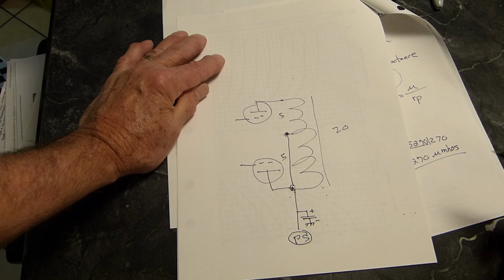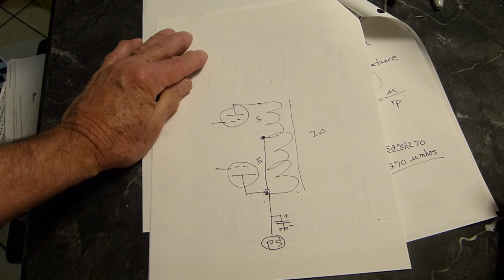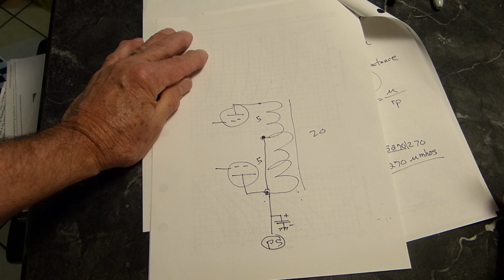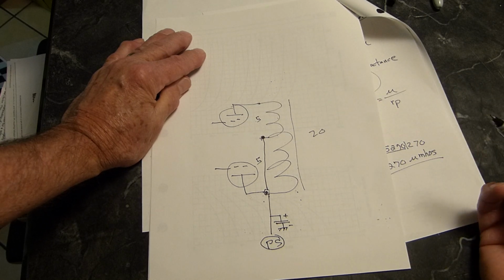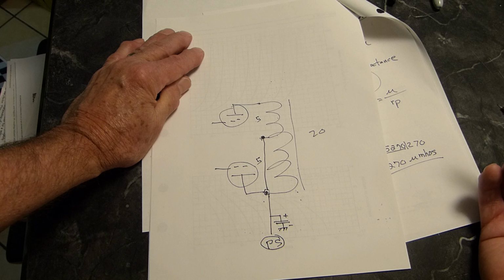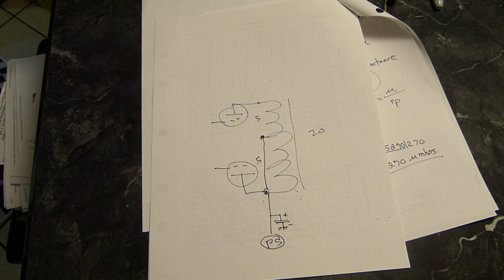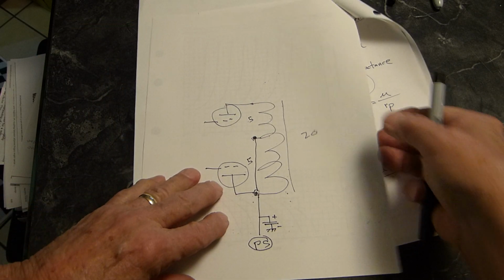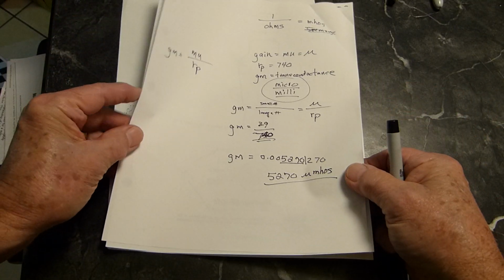So your 20 Henrys or 40 Henrys or whatever, I've been there. I've been obsessed over this until I actually had to figure it out. But my tube is operating across 5 Henrys, and people get really obsessed about this and think you need 40 and 50 and 100 Henrys like in an SET amplifier. Well, think about it, and you may realize that you just may not be taking everything into account.